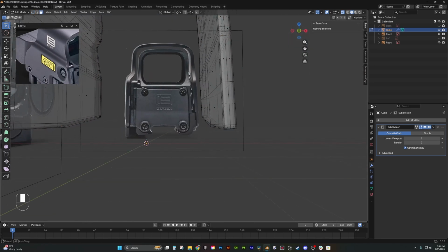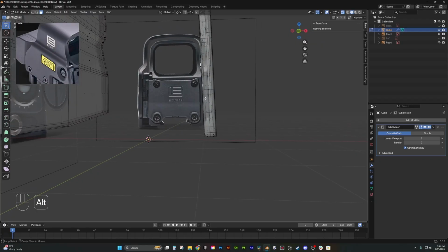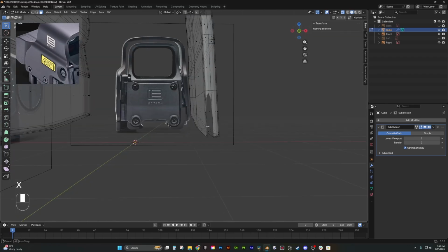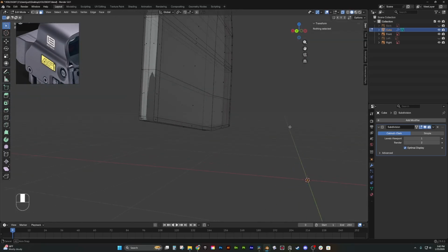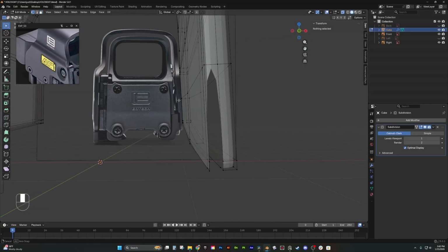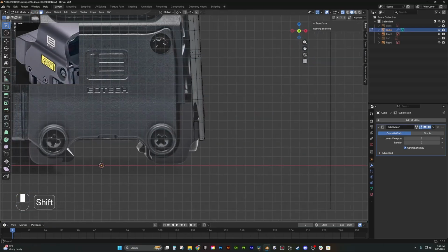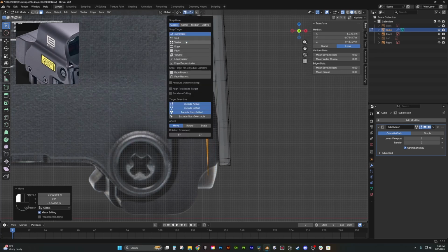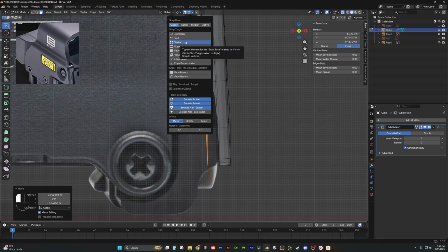So this is one of those situations I was talking about where you're nearly rebuilding this entire piece. So I'm grabbing these faces and I just deleted them. Let's make sure we got all these side ones. And so while this isn't a perfect method, what I'm going to try to do instead of having to rebuild each face one by one is I'll grab these faces right here and press a new key called Y, and that separates them.